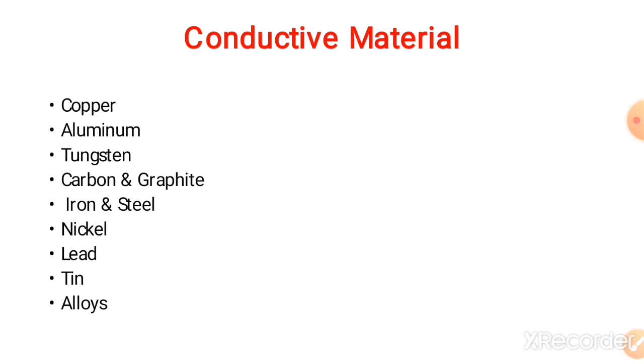Next material is iron and steel. Steel is employed in railway applications for its cheapness and rigidity. Galvanized steel and iron wires are generally used for earth conductors in low voltage application systems. They may also be used as phase conductors in rural areas where cheapness is the main consideration. Such lines will have large voltage drop because of their high resistance and inductance.